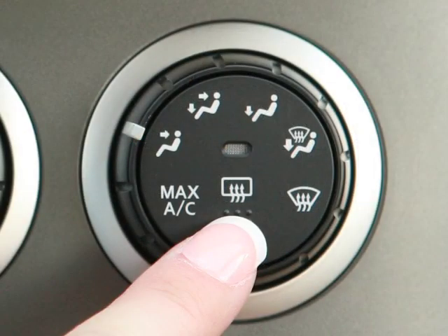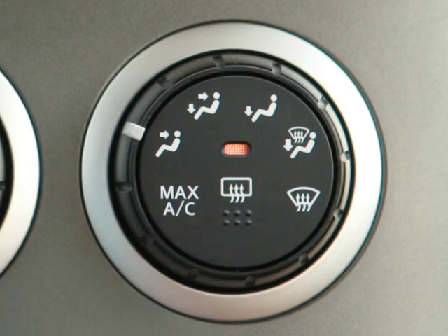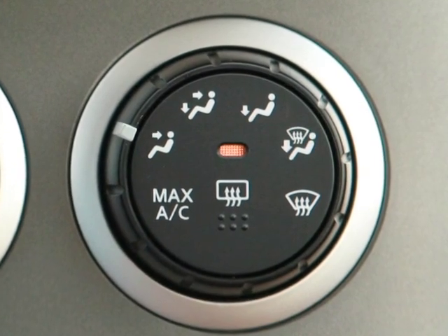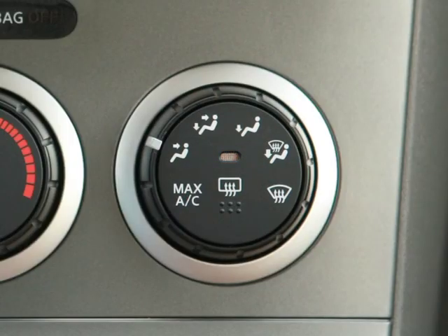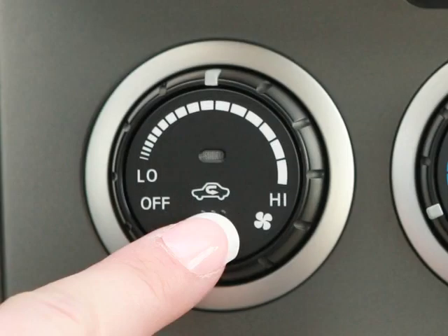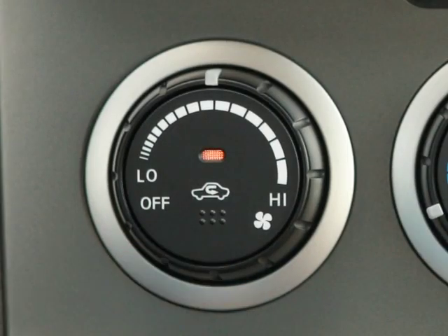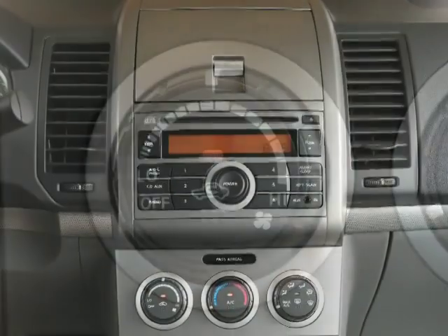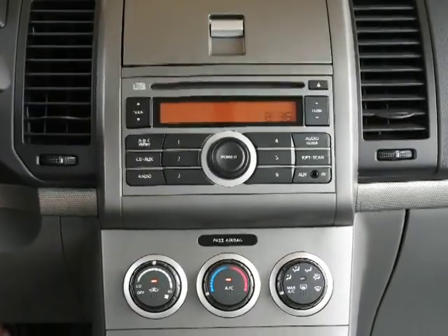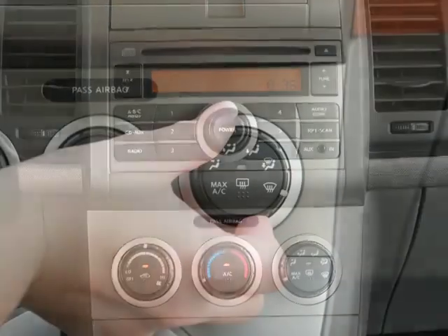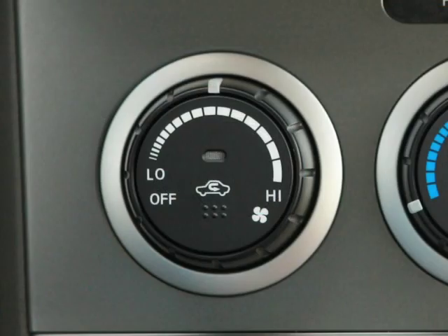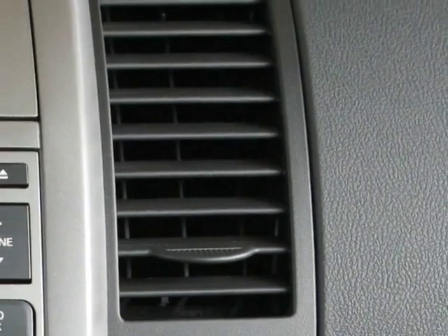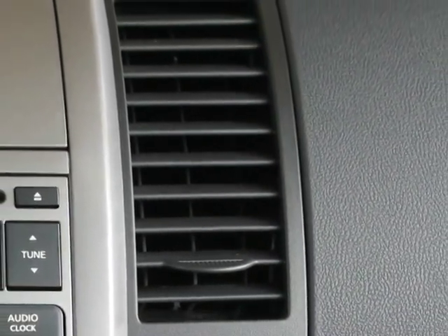To defrost or defog the rear window, press the rear window defroster switch. After defrosting, press to turn off. It turns itself off automatically in about 15 minutes. Press the air recirculation button to circulate air inside your vehicle. This helps AC efficiency and blocks outside odors from entering. Please be aware that if the airflow control dial is on defrost, the air recirculation feature will not activate. Allowing outside air in helps the defrost-defog process.